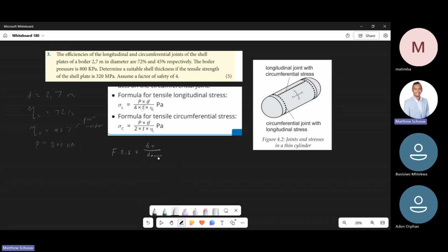We need to first solve for the allowable stress. This is mentioned in the first chapter. I'm not sure if you've had a look at that. But nevertheless, we need to find our allowable stress, which is quite easy. That's going to be simply 320 divided by the 4, which is given. I'm just manipulating this equation over here. If you do this, you should get 180 megapascals.